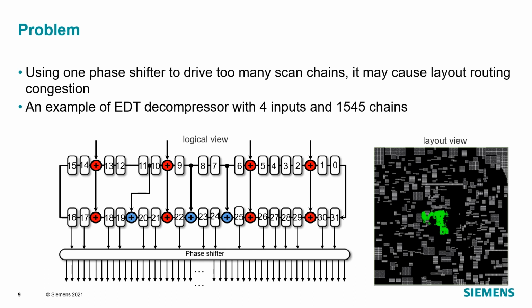In the development of the algorithms, we wanted to make sure that while targeting reduction of routing congestion, the encoding efficiency of the segmented decompressor remains very close to the single monolithic one.